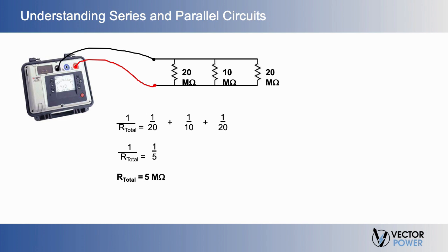For example, using the following formula to determine the minimum insulation resistance value in megohms to a 100-foot nominal value, the minimum megohm value would equal 100 divided by the busway or cable length in feet. As we can see, adding sections or length introduces more parallel paths.